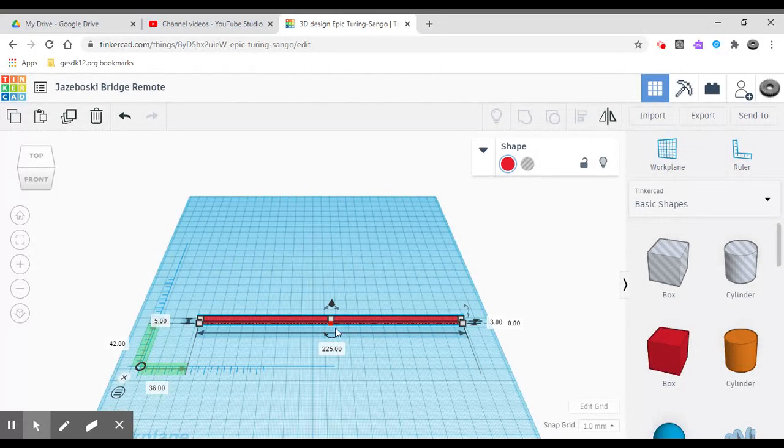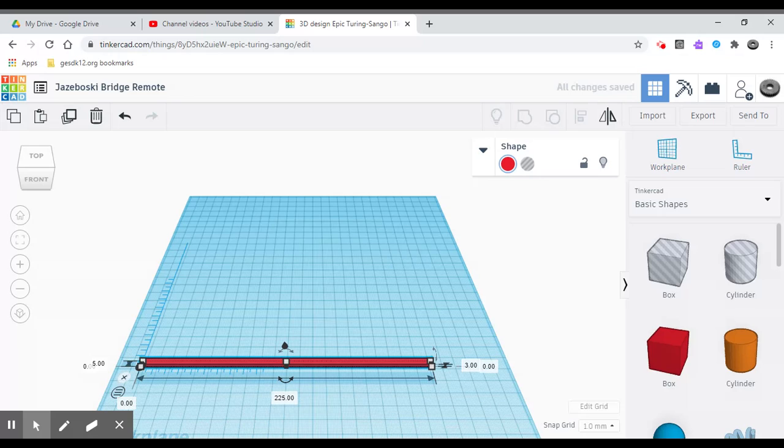After we have the bottom beam created, we want to zero it up with our ruler. We want to bring it to 0, 0 on our XY axis. To do that, we have these bottom points. There's our x-axis number, and you can see there's this little green area here, and when I put my pointer over it, it turns red, and we have our y-axis in green there, and the same thing happens. So we'll start with our x-axis first. We're going to click on that and change that to 0, and you see how it slid it over. Then we want to bring this part down to 0. We're going to click on that, type in 0, and now it's at the 0 point. So we're lined up with the ruler.